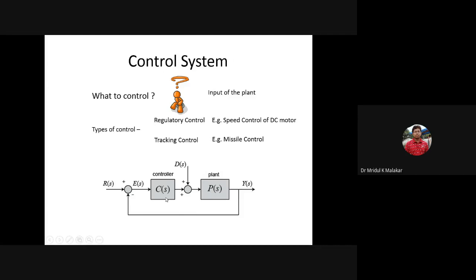Another one is the measurement. You are taking the measurement, but who knows whether you are measuring the absolute output of the system? You don't know. Maybe there is some little offset. Suppose you are measuring 310 rpm, but you are giving 300 rpm. Somehow it will deviate from the reference, and it will try to apply some erroneous value to the control system.